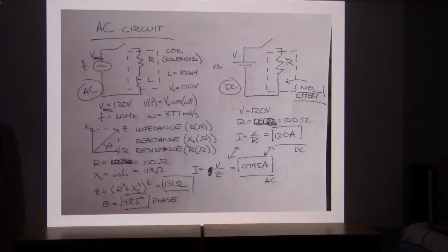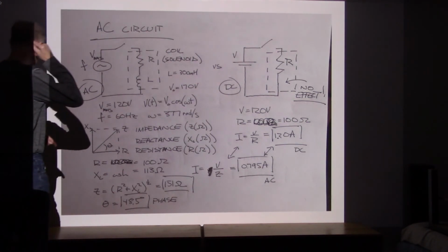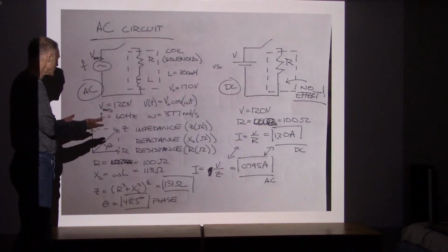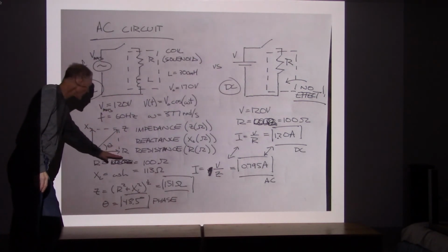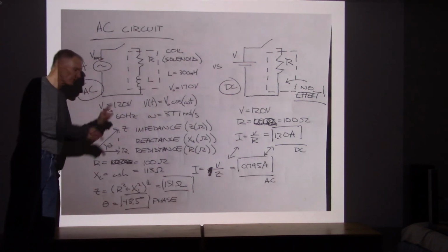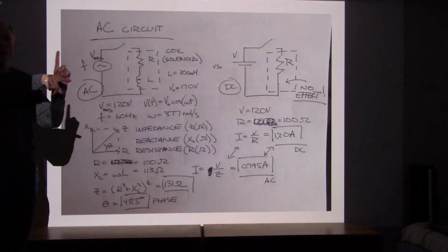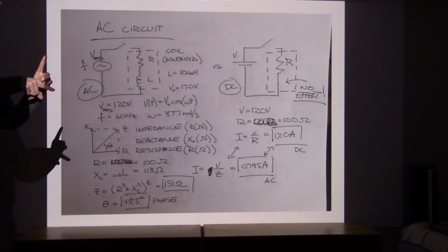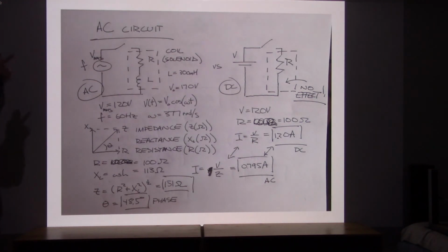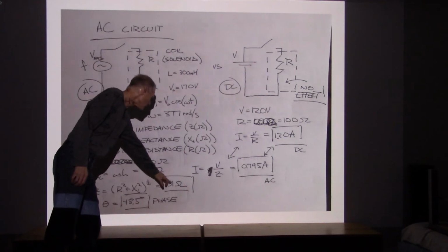So there, that's a little different, but first of all, it's not too difficult, and it's keeping track of all the phase differences that are taking place. Since I have those nice 90-degree phase differences, I don't have to do components necessarily. What I have is distinct components that line right up with the x and y directions in my impedance diagram. And so Z is just the hypotenuse, and that's at 151 ohms.